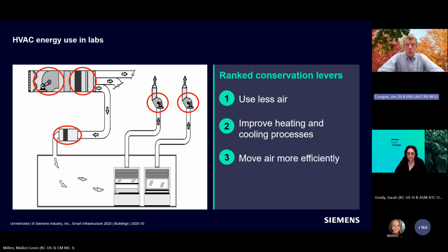The circled elements here are where we're consuming the energy. Electricity to drive the fans, hot or chilled water that was generated by other kinds of fuels, electricity or gas. And this is where we consume the energy. Knowing that, we can think about how it gets used up. The fan energy is really sensitive to the amount of airflow. It's not just linearly increasing with the airflow, but it increases somewhere between a second and third power of the airflow. So fan power is very strongly affected by the quantity of airflow.